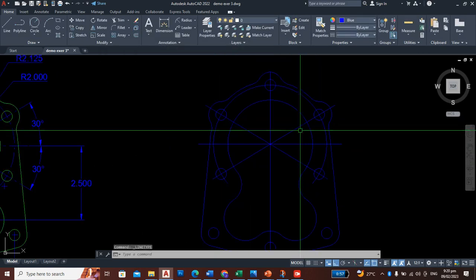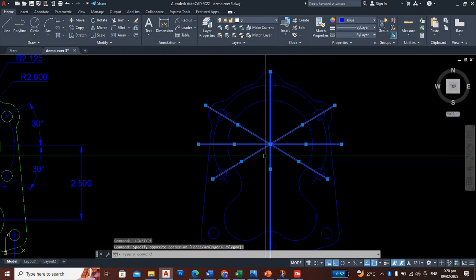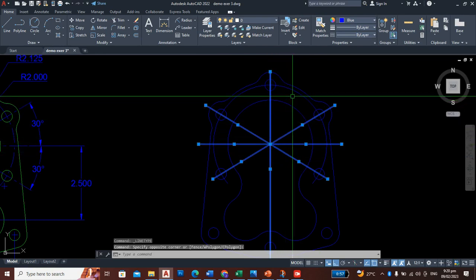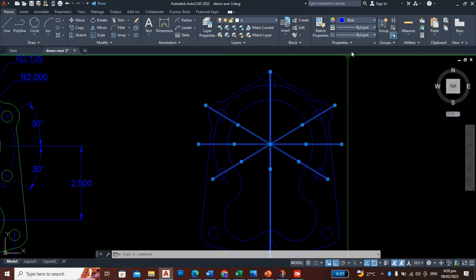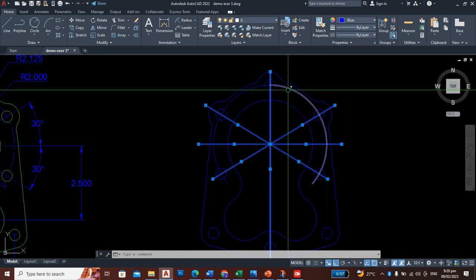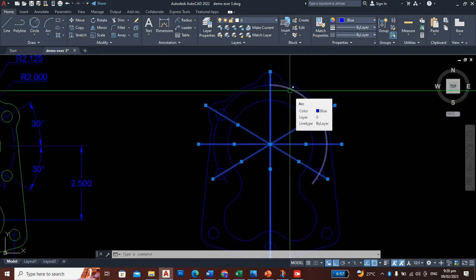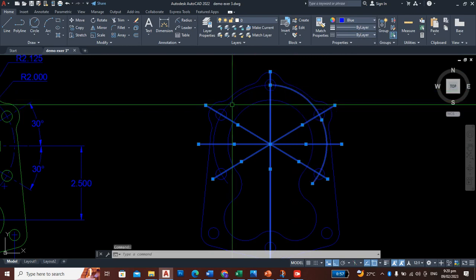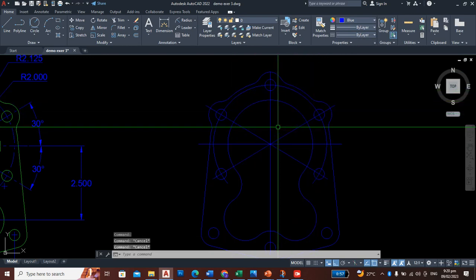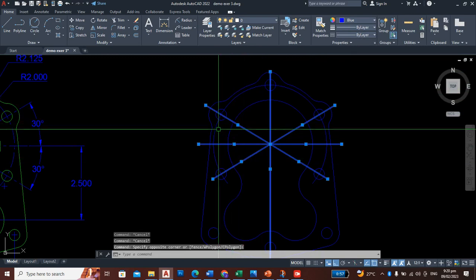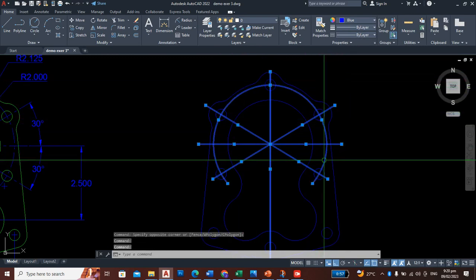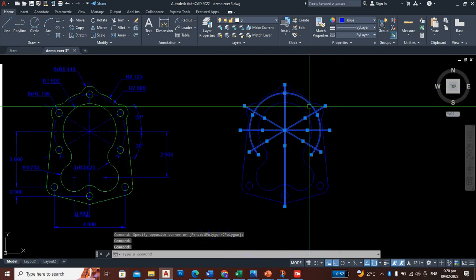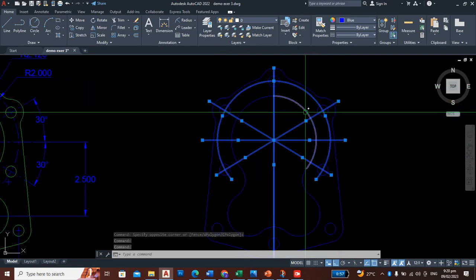Now select again, because earlier we needed to load, so the selection was cancelled. Okay, so just cancel again, select again the lines that will be assigned the line type center line or center.